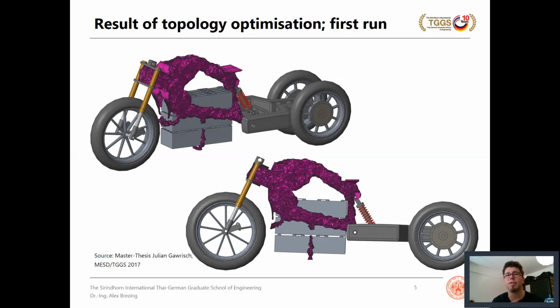But again, I'm not a big fan of this. So typically the workflow is you run these simulations, then you understand the results, and then you redesign it in CAD, approximating whatever the FEM software came up with, and at the same time considering other constraints like what is possible with the chosen production procedure, could be draft angles, and so on and so on.